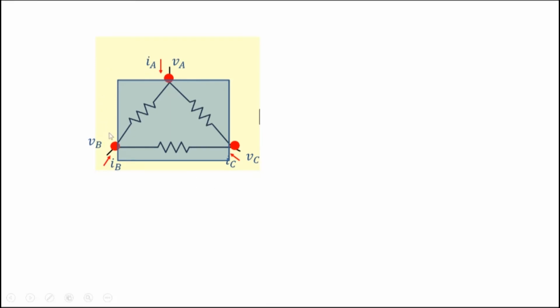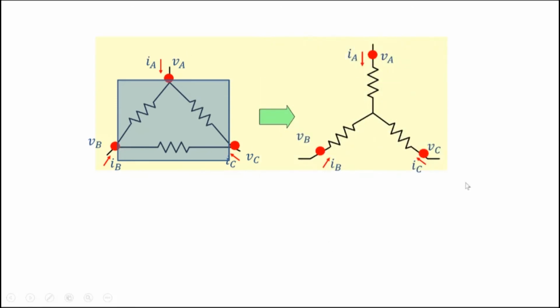So what we are saying is, if you look from the terminals' point of view, this circuit can be converted into this circuit here. This circuit is equivalent to this circuit. In what sense? Well, if you apply VA, VB, VC here, currents IA, IB, IC flow. If you apply VA, VB, VC here, the same currents IA, IB, and IC flow. Exactly the same current would flow here. So in that sense, from the terminal current-voltage characteristics, the two circuits are similar.